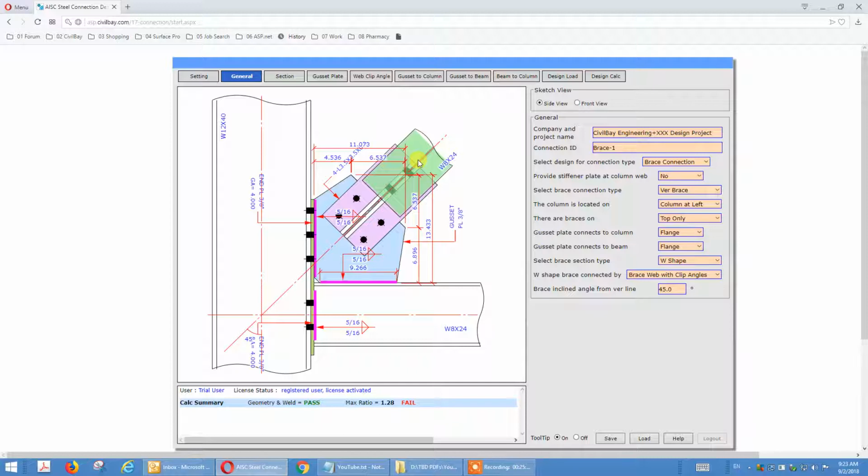That's my way of designing. Okay, some engineers might argue, hey, the tensile brace is always acting as a brace point for the compression brace. I couldn't agree with that. I always take the in-plane brace length to be half and out-of-plane brace length to be full.